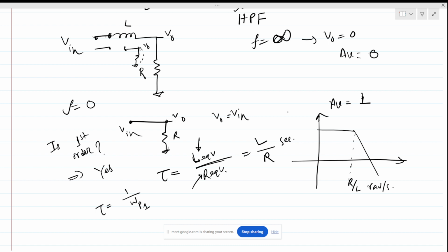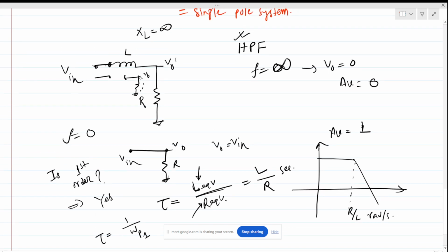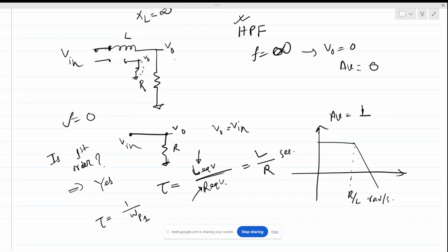Actually, why are we not talking about inductors so extensively? Because in an integrated circuit, to make an inductor is very complex, and to make a high value inductance is also complex. So we are dealing with capacitors only, at mid range frequency. We always try to do the capacitive behavior analysis of the circuit, using capacitance.